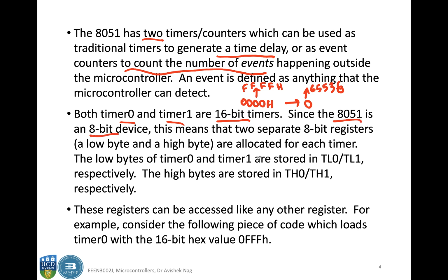So this means that two separate 8-bit registers are allocated for each timer. The low bytes of timer 0 and timer 1 are stored in TL0 and TL1, and the high bytes are stored in TH0 and TH1.